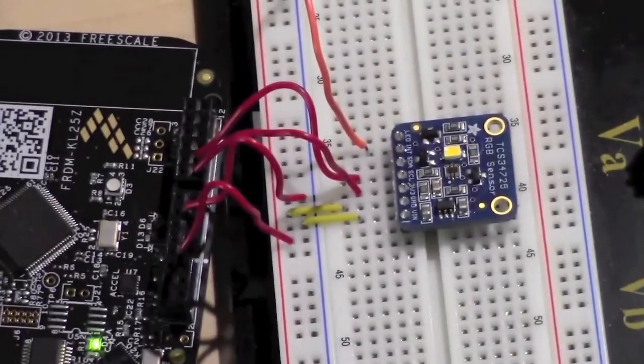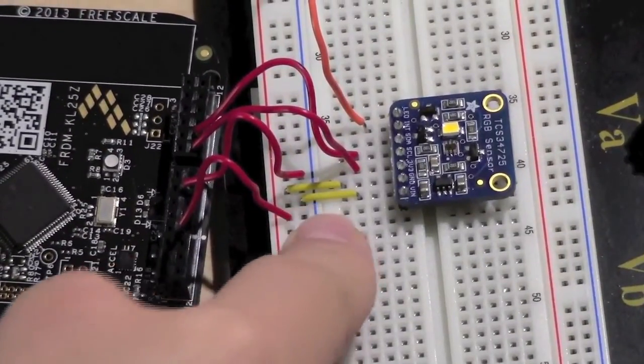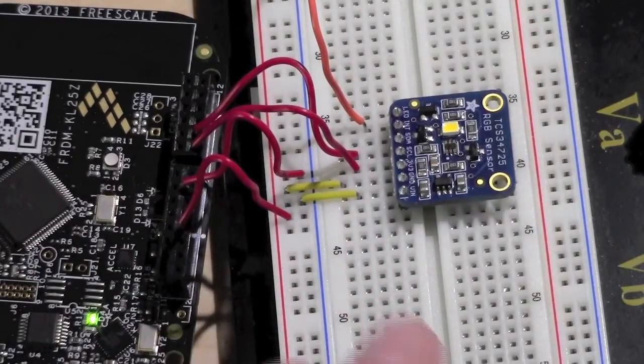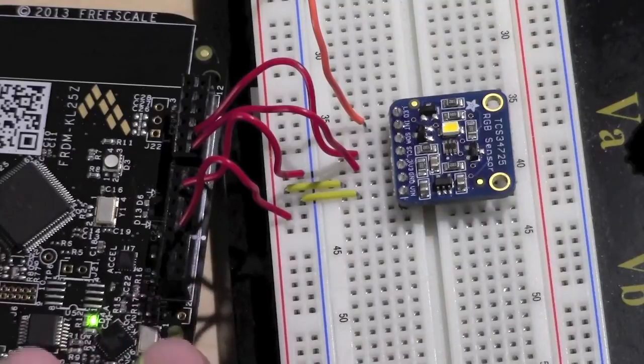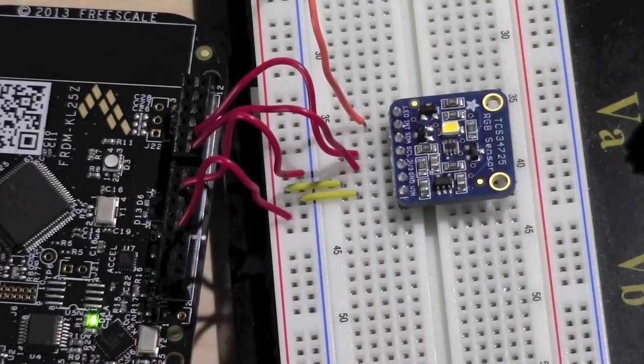Again, you just connect the power line, 3.3 volt line, ground line, SDA, and SCL to the respective pins on the microcontroller, and this should be good enough. So we're going to write some code up to interpret this. But before we do that, we should read the specification sheet, so we know exactly what registers we want to program, and how to read out data from this chip in particular.